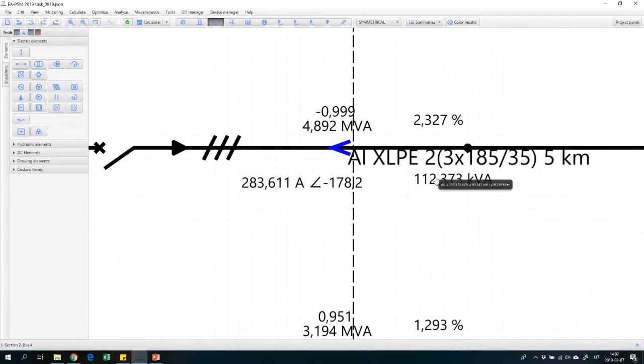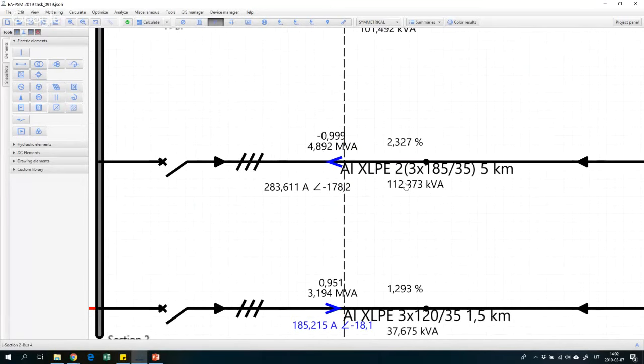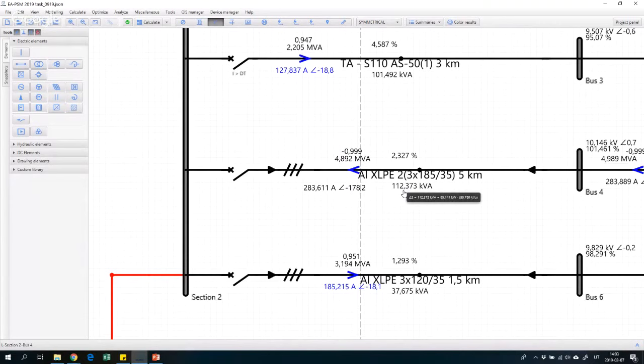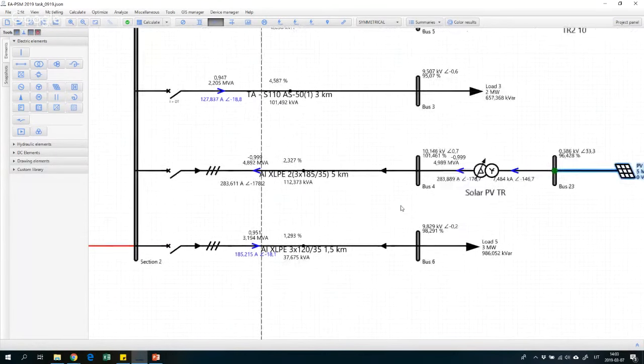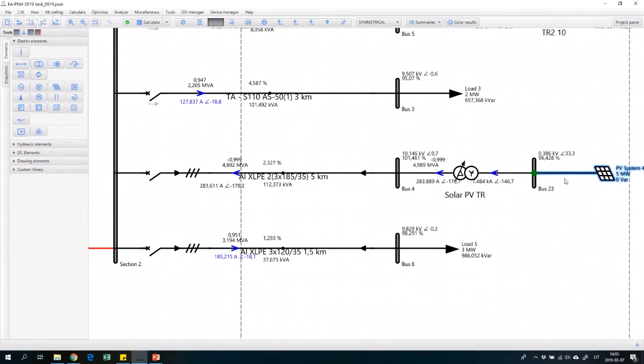It's 95 kilowatts now instead of 110 kilowatts, and my voltage losses are also a little bit smaller. Of course, not that much, because the current changed only by, let's say, 12 amps. However, my active power losses are reduced significantly, which is again an important finding, to see how active power losses and voltage losses are affected by the active and reactive power balance in the network. So with this kind of software we can do this analysis, of course.